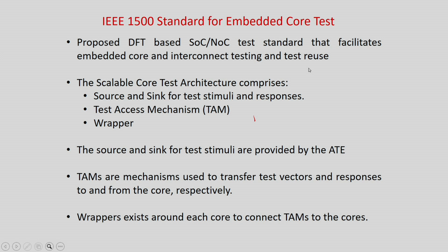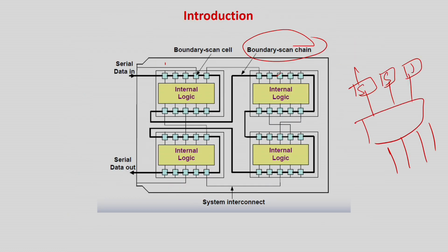That is the core idea, that it will test the internal logic as well as the interconnection, because as I told you, the vendors will have sold it to you. With the internal logic to be tested, they will give you the test patterns. But it is my duty to test these internal lines, the internal connections, because I have taken the cores and integrated them. My job is to use the patterns given by you to test the internal logic, but the internal interconnects I have to test.